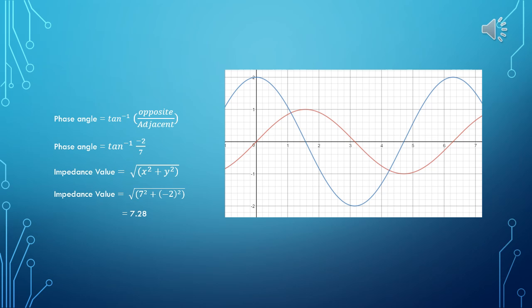Being able to calculate this angle is useful in real life. If a circuit is found to be too inductive, energy consumption and bills will increase. By adding capacitors, we can reduce the angle of theta and therefore reduce unnecessary power consumption. Finding the total impedance value of the circuit is just a matter of using the Pythagoras theorem in the real and imaginary coordinates.